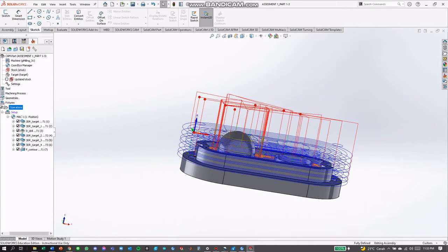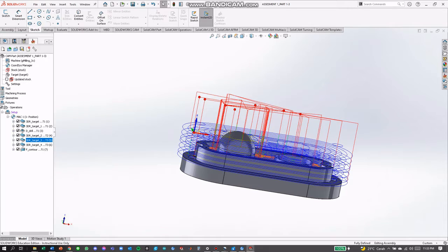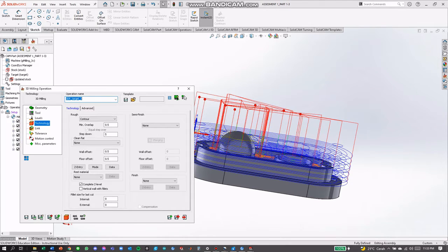Oh, my mistake. For the spherical shape, we want a better finish for it. So we need to have them overlap, and then we'll offset to be smaller, because the step down is how many turns the mill will do to make the part itself.